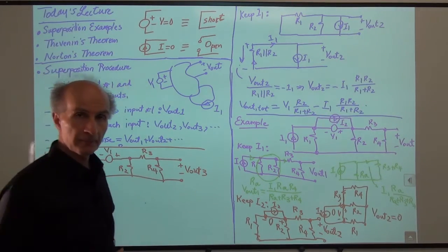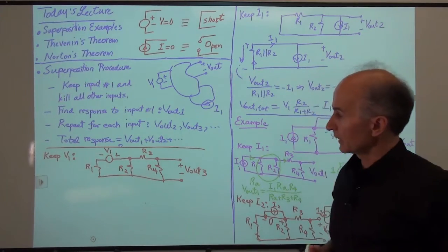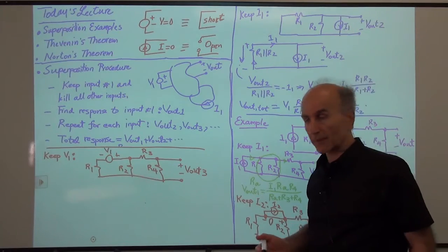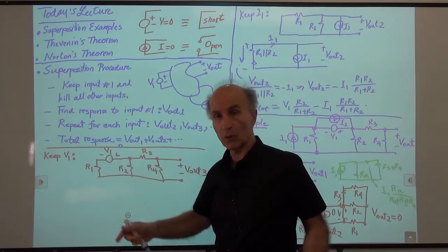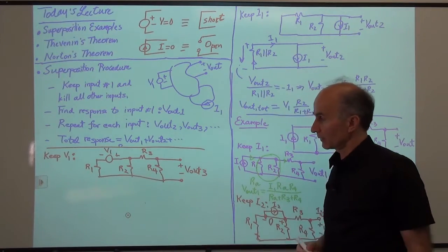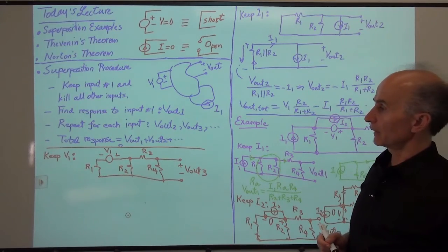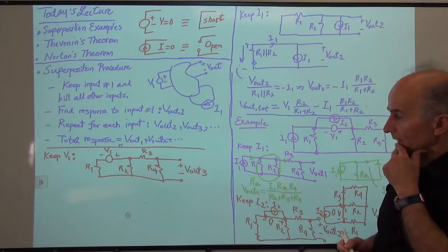All right. Well, again, we have to see how we can solve the circuit. You can definitely write node analysis or mesh or something. If it's node, then this will be a super node. It's just to merge into one. It's not that hard to do that. Or we can try to see if we have any intuitive simplification.